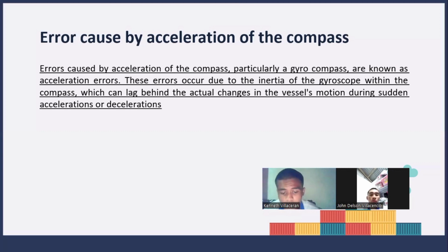Directional effects: the direction of the error depends on the compass heading and the hemisphere you are in. In the northern hemisphere, acceleration on easterly or westerly headings causes the needle to indicate a false turn towards north.